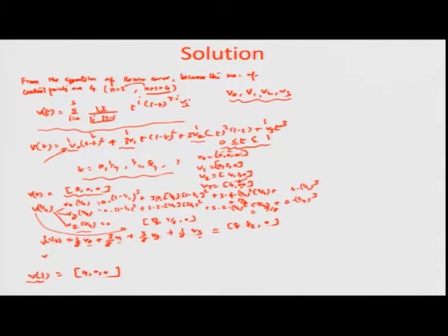And similarly, we could do the same for V 3/4, where the final formulation would be 1/64 V 0 plus 9/64 V 1 plus 27/64 V 2 plus 27/64 V 3, and then if we substitute again x, y and z values of all these 4 different points, we are left with coordinates 27/8, 9/8 and 0. So, we have now plotted whatever falls on the curve.